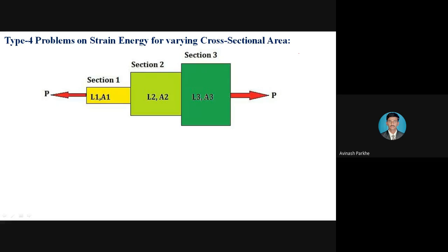In that, the deformation is given, that is the elongation of that particular collar or rod. In addition to that, the falling height is also given, and by using the deformation formula we calculated the stress induced in that particular rod, and then by using that stress we calculated the unknown weight which is falling from a certain height.